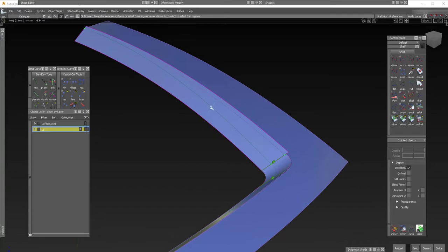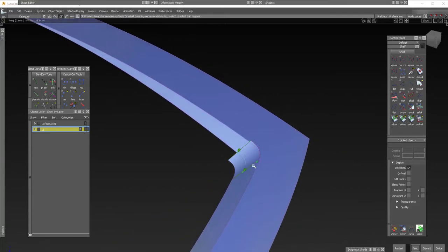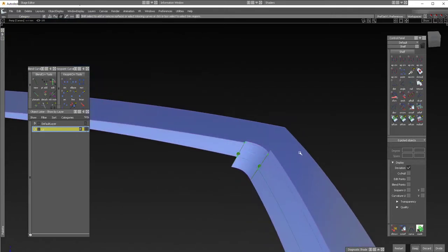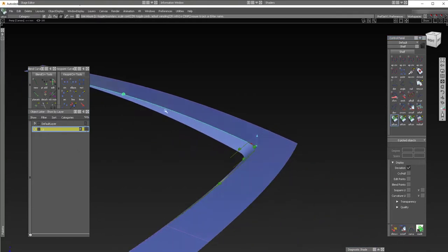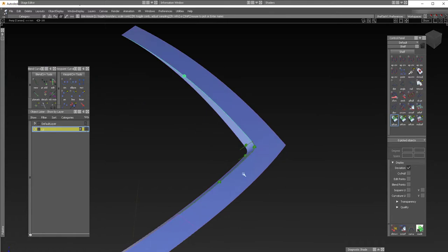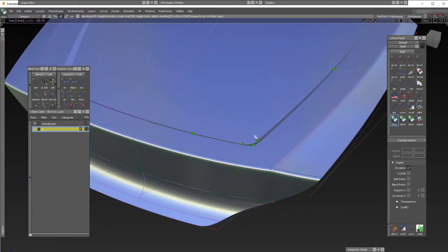When I control-mark, let's say you have so many of them, just click restart and pick again. Right now we have positional continuity all across the edge. So this is something essential before creating the surface fillets.